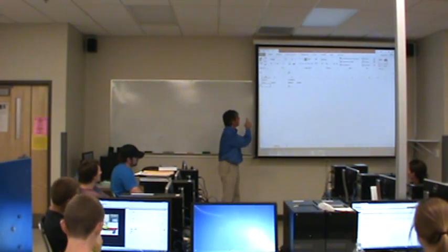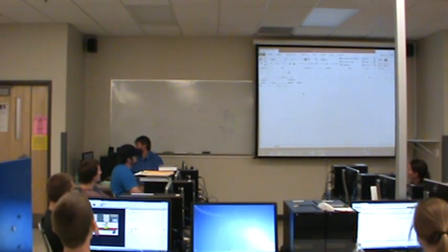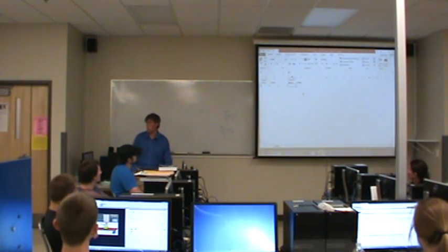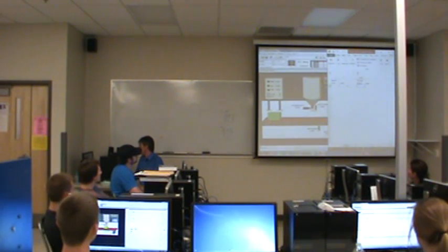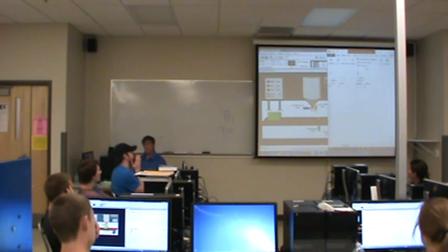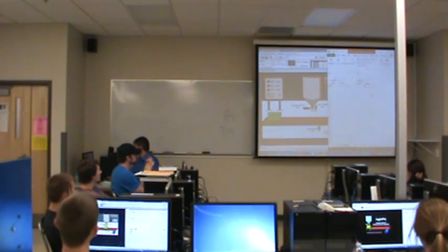Okay? So what do we want to see? Well, we want to see that there's no box in place, that it's not full. All right? That's what we're looking for. When we see that, what should we do? Let's go back and look at the system. When we see that there's no box in place and level's not true, what do we want to do? What output should we turn on? Should we turn on valve? No. So that's the response.